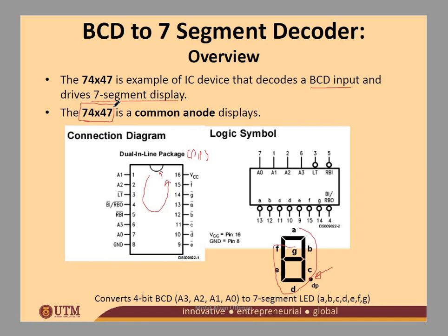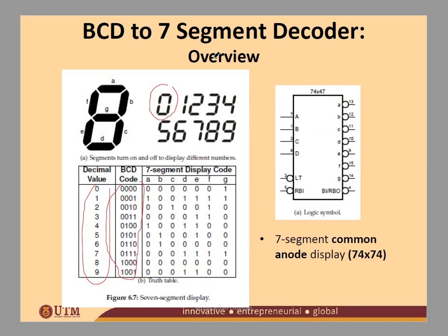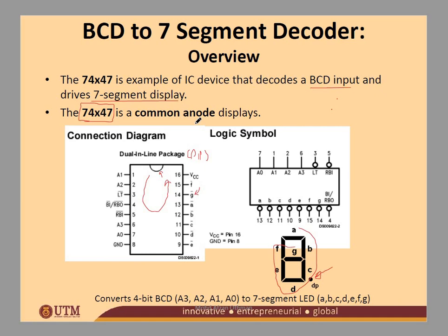If you can see here, they are active low outputs. So when you see the bar here, you know that those with 1 are not active, meaning they are not displaying, because we have an active low output display.